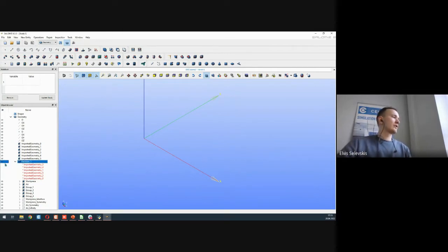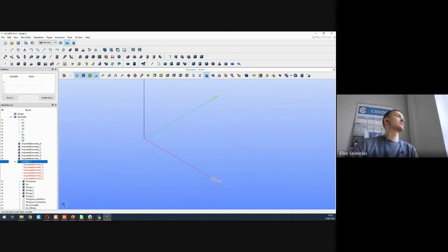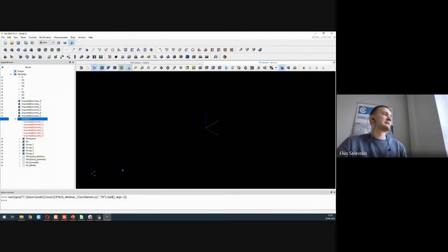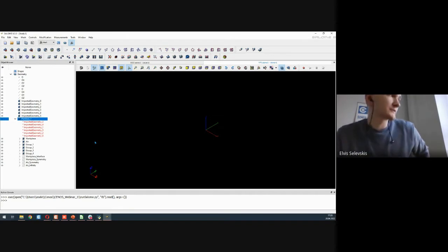All right, now we are ready to go to the meshing section, since all of our small groups are made. Line groups are made for the physics, so that's all good. To go to the meshing, we can press the button up here. And what we will proceed with is splitting all of our geometrical objects, so the workpiece, inductors, also air, into triangles, so that the electromagnetic calculations afterwards have an easier time of doing all the calculations. Because as we know, for a triangle, we can pretty much calculate anything which we want to. So that's why we need to simplify our geometry into these triangles.